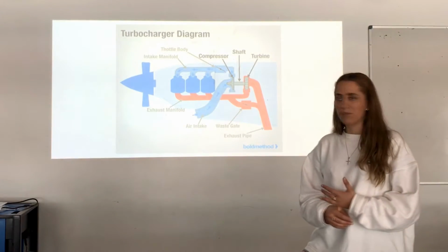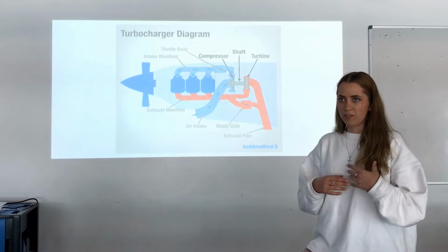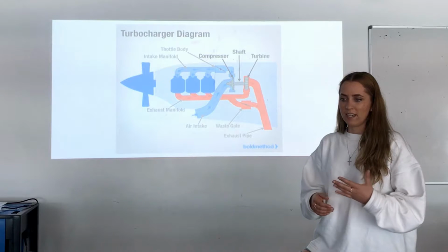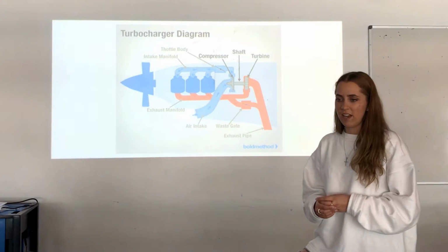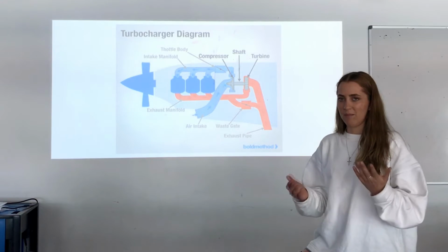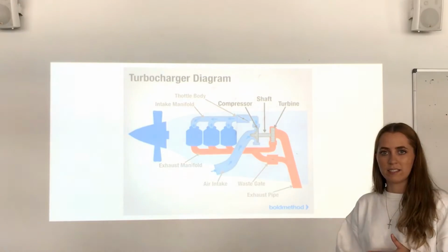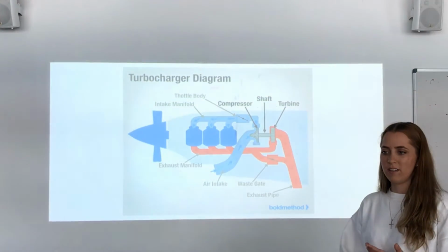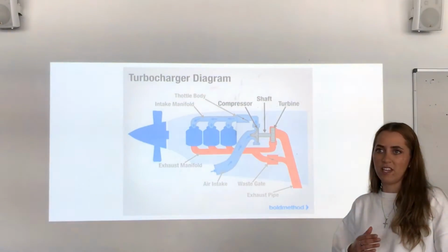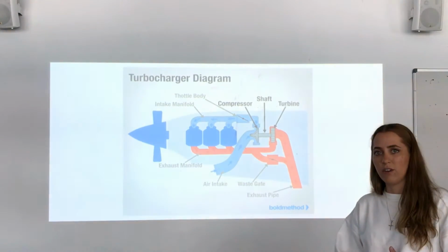The main purpose of the turbocharger is that it will produce a boost which will maintain desired manifold pressure at a given throttle setting, regardless of the altitude or the ambient air temperature and pressure. However, this can only be maintained until a critical altitude, and manifold pressure can then no longer be maintained, which means the aircraft has reached its critical altitude.